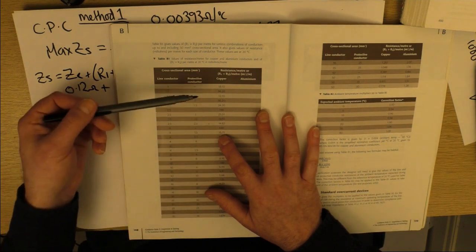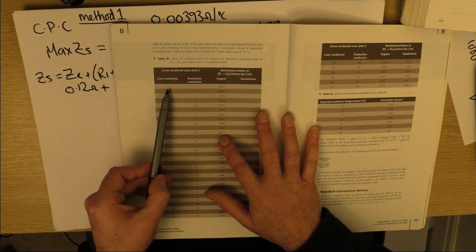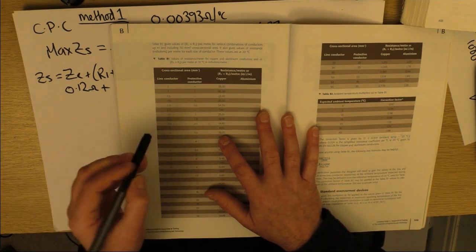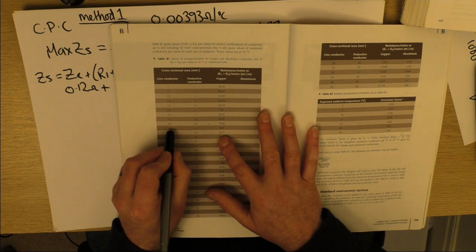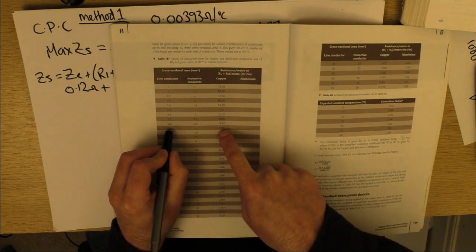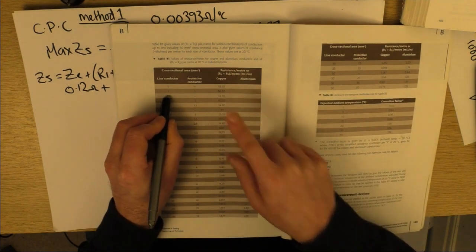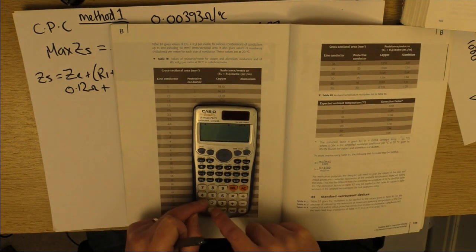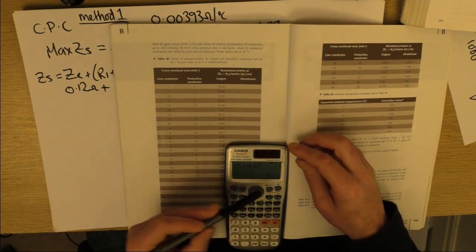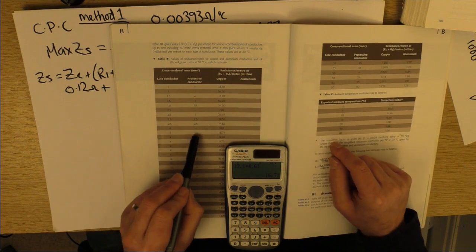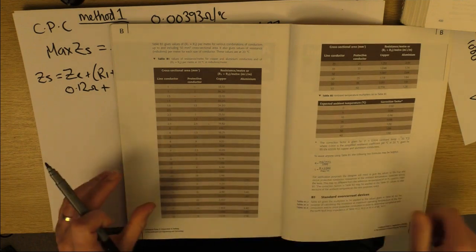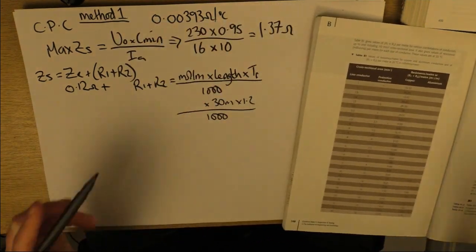So, this is a handy table. It gives you individual conductors, but it also gives you these handy combinations. So what I could do is just take the 4 mil on its own value of 4.61 and add it to the 1.5 value of 12.10. So 12.10 plus 4.61. What do I get? I get 16.71, which is the same, isn't it? So they've done it for you. Again, cheers guys. Just makes my life so much easier.